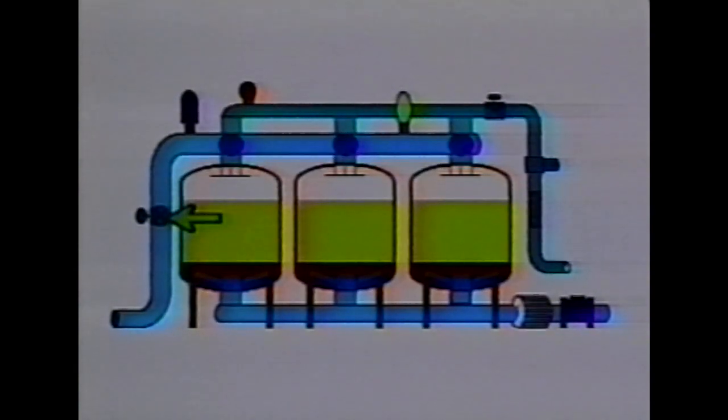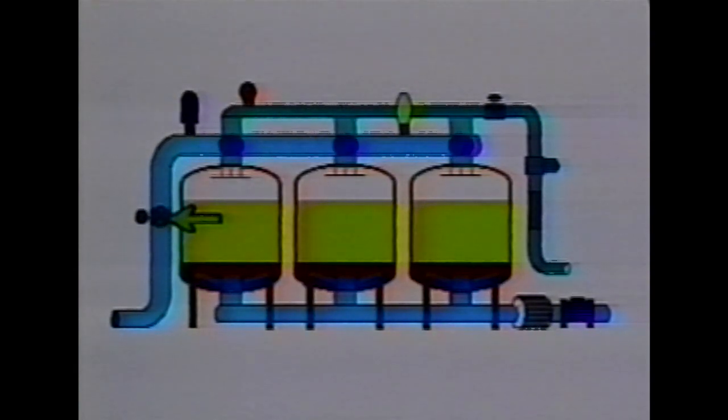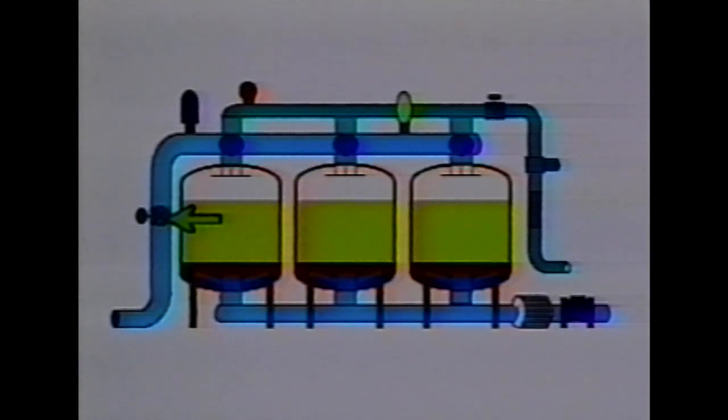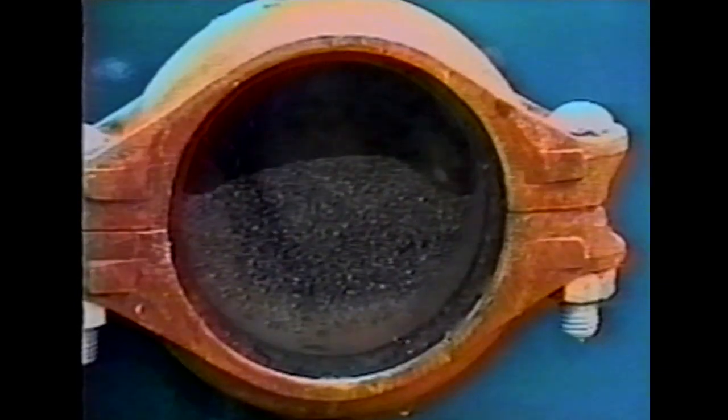A rinse valve is necessary upstream of the filters for some installations. The rinse valve is only used during the initial cleaning and backflushing of the filters. Media and gravel, when purchased, often have a high percentage of fine particles which could pass through the tank underdrains and into the irrigation system.